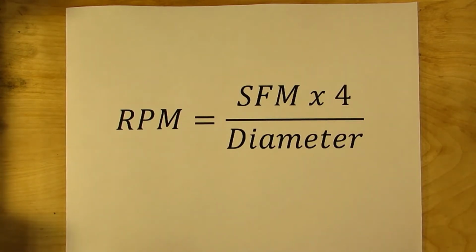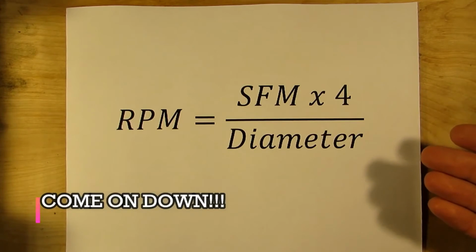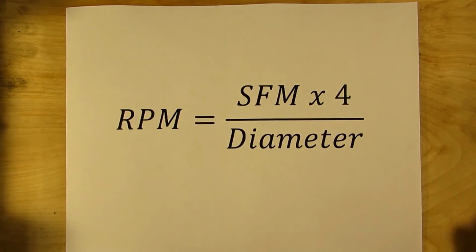Now in those cases where your calculated RPM is one thing and you don't have the exact option, you want to follow Price is Right rules. That means you're going to choose the closest one without going over your calculated RPM. So if you calculate your RPM at 1440 RPM and you have a choice between 1115 and 1750, you want to choose the lower of the two. You want to choose the 1115 because if you run it at 1750, you're actually machining at a much higher SFM and you might burn up your tool.